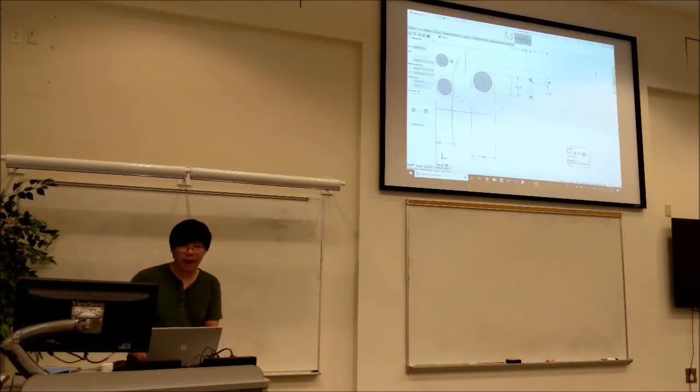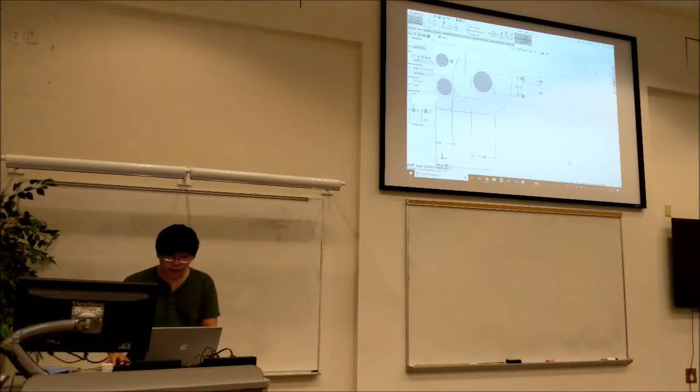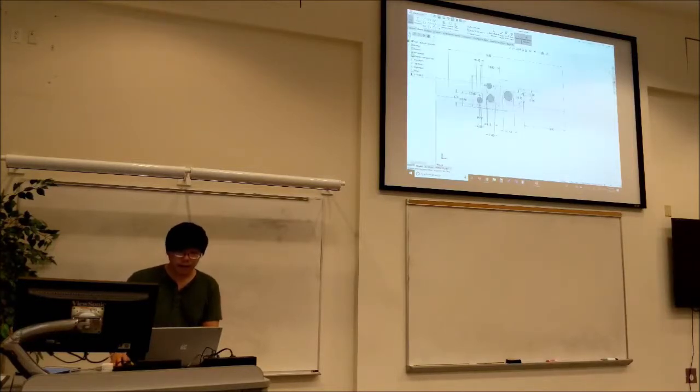Because we do a half inch spacing between our holes, we want this to be an increment of 0.5. So I think we can do 5.5 here. This is where our holes are going to be in the plate for us to put the standoffs through.